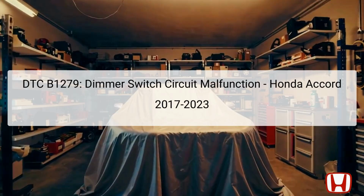The DTC B1279 indicates a malfunction in the dimmer switch circuit of the Honda Accord models from 2017 to 2023. This error is crucial as it affects the functionality of the headlights, which are essential for visibility during nighttime driving and in low-light conditions. The Body Control Module, BCM, monitors the signals from the dimmer switch, which controls the lighting levels of the vehicle's exterior lights.